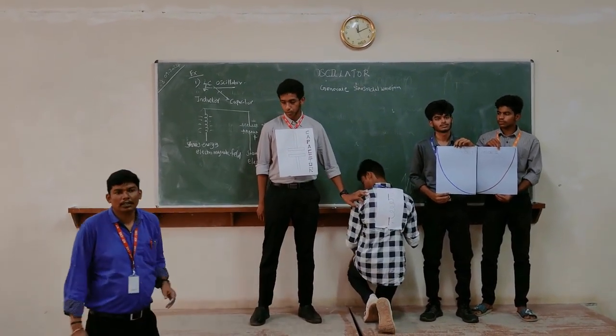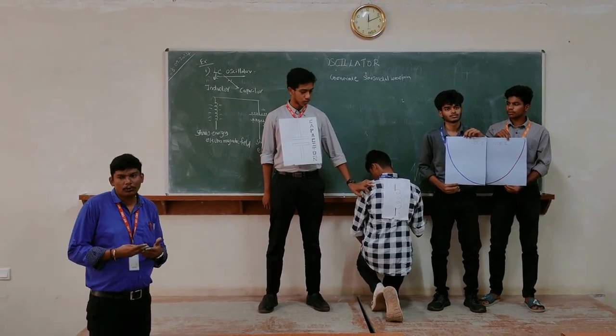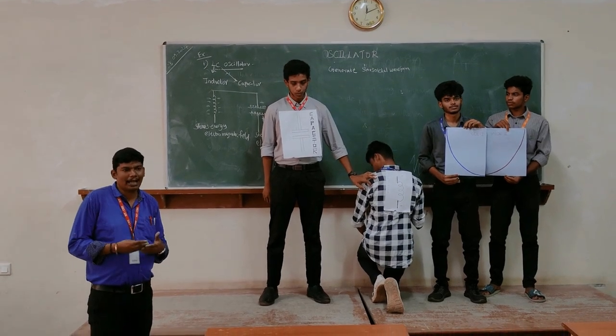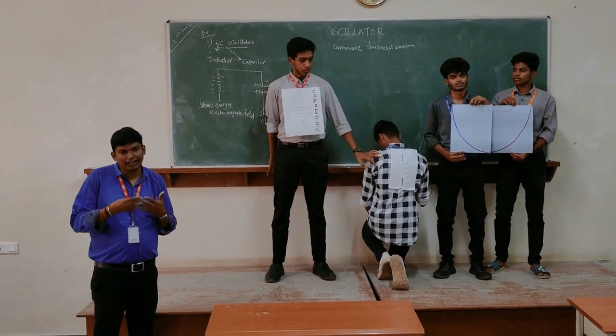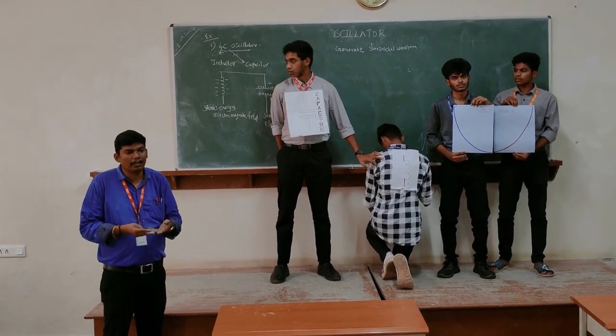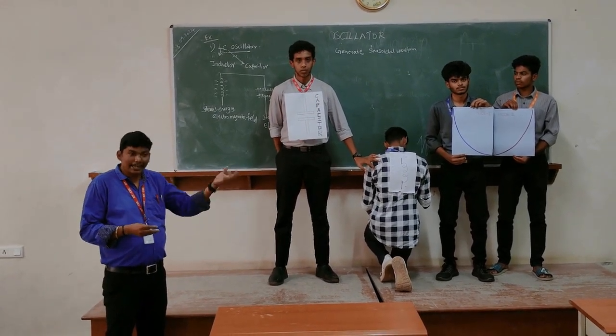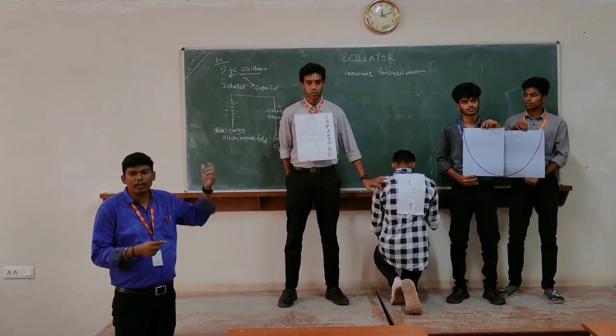Now what happens after the operation of mode 2? The inductor no longer has its energy. All the energy has been transported in the form of the electromagnetic field, so the capacitor gets its energy as static electricity and can be charged fully.